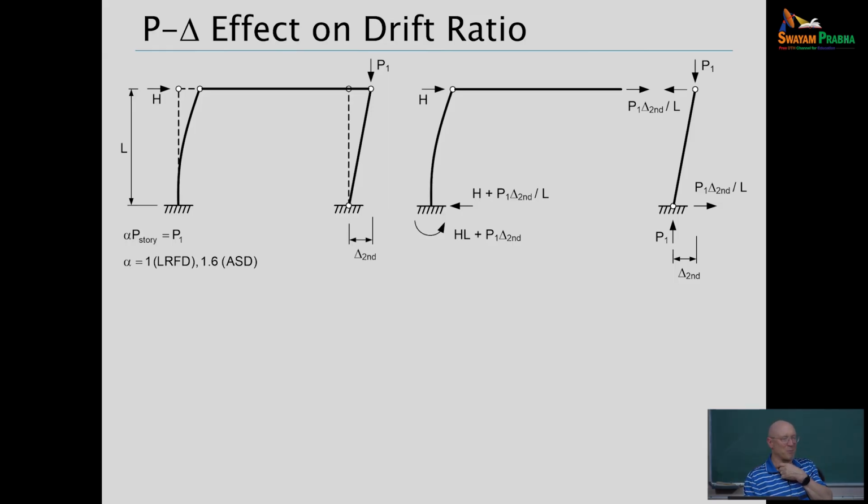There were a number of prominent engineers, practicing engineers, and some academics on the AISC specification committee, and it was observed that the load factors in ASCE 7 for allowable stress design were such that with certain wind load or earthquake load dominant cases, you could literally size a member or a structure with about 2/3 the size of what LRFD would require.